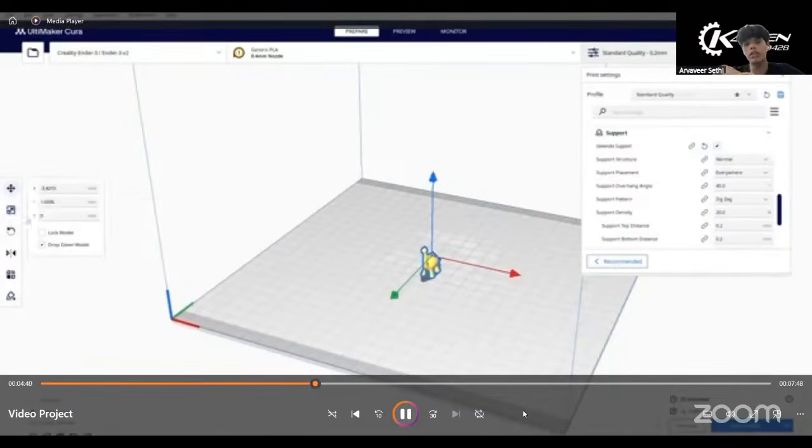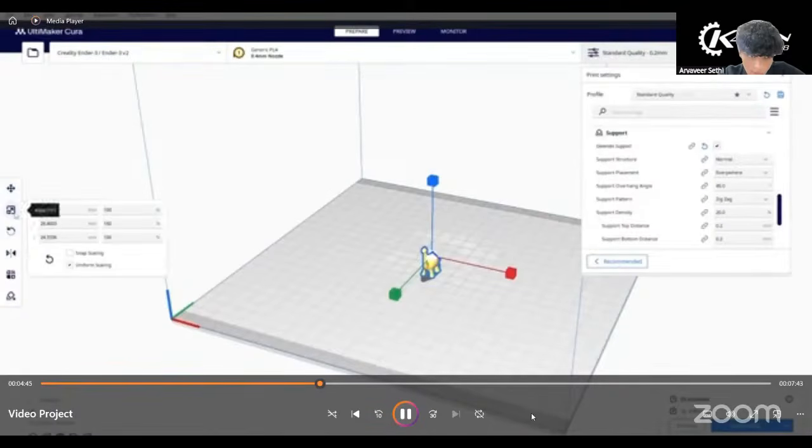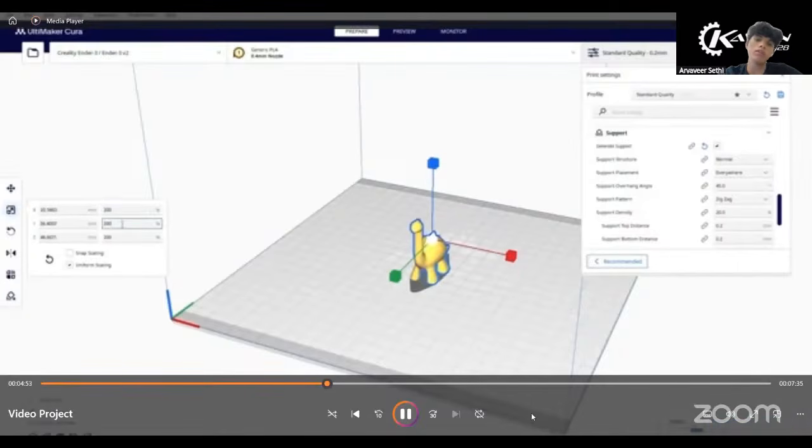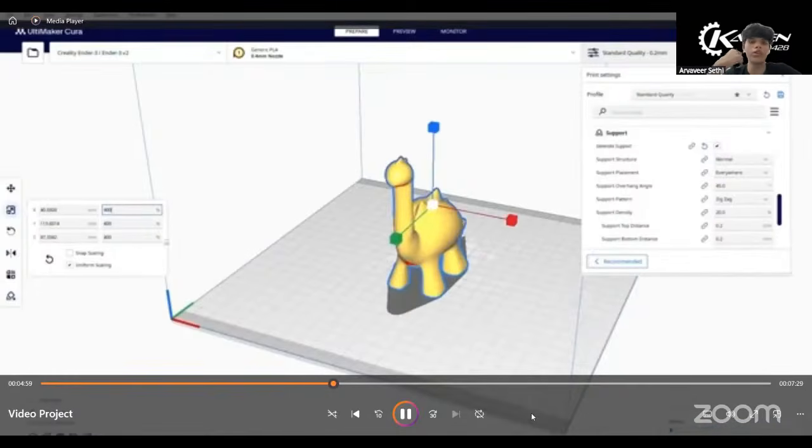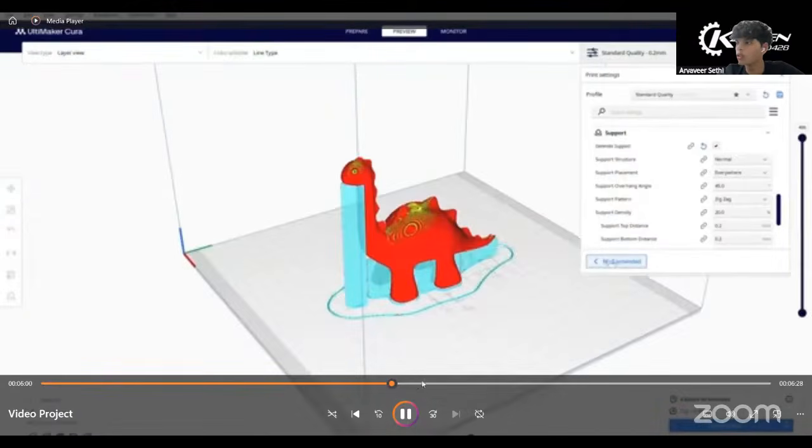So once we have the STL file, we can upload it into Cura, and here we can change a few things. As you can see, we can change the infill percentages, we can change some of the dimensions. We're going to have a low infill percentage for this because obviously this is going to be a decorative part. We're not going to be able to use this in any robot. And as you can see, I've increased the size of this object, and I can move it within the three axes. So you can make a lot of different changes to how this thing works.